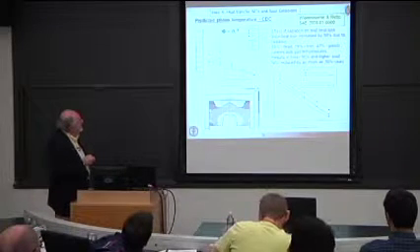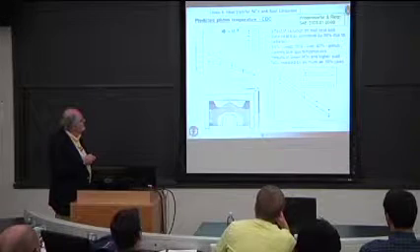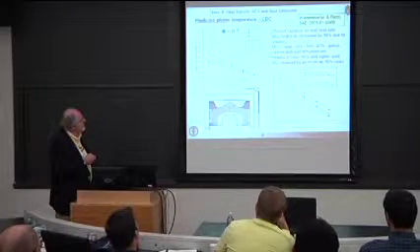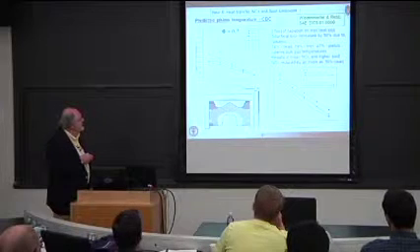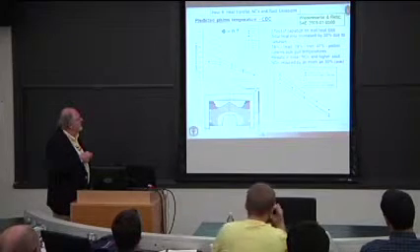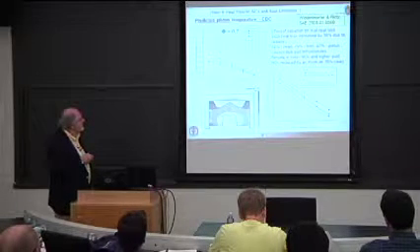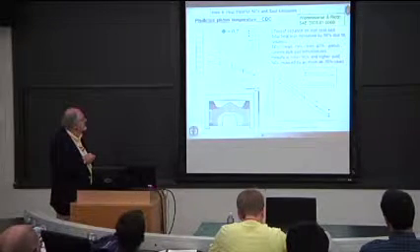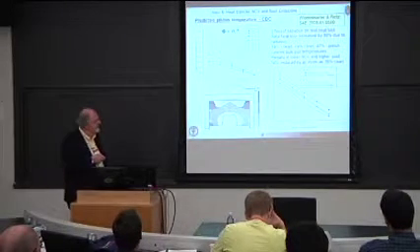So the solid lines here are when we do not include radiation in the heat flux calculation. The open symbols, though, are when we do include radiation. And you can see significant impact of radiation on surface temperatures. So we go basically from 600-something degrees, 630 degrees for this case, all the way up to 700 degrees by including radiation in the heat transfer.